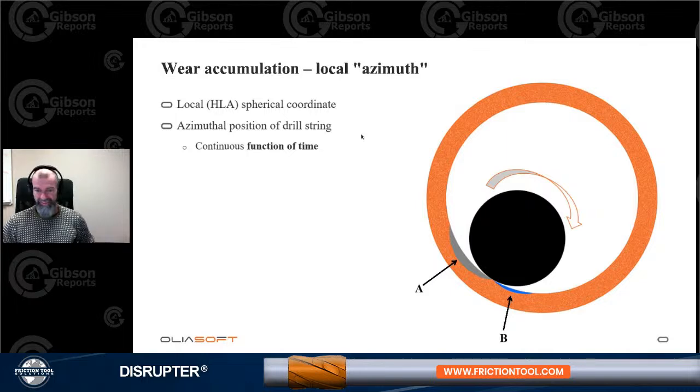So now the next important part is that we have basically looked at how we can calculate wear on a small piece of a component. And obviously we have several hundreds of them to reach our depth, to reach our TD. And we need to accumulate all of these small segments that we have calculated the wear on.